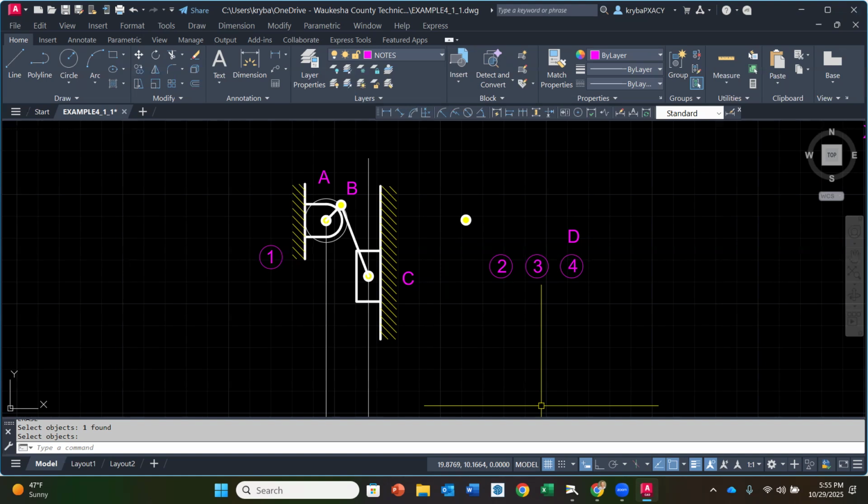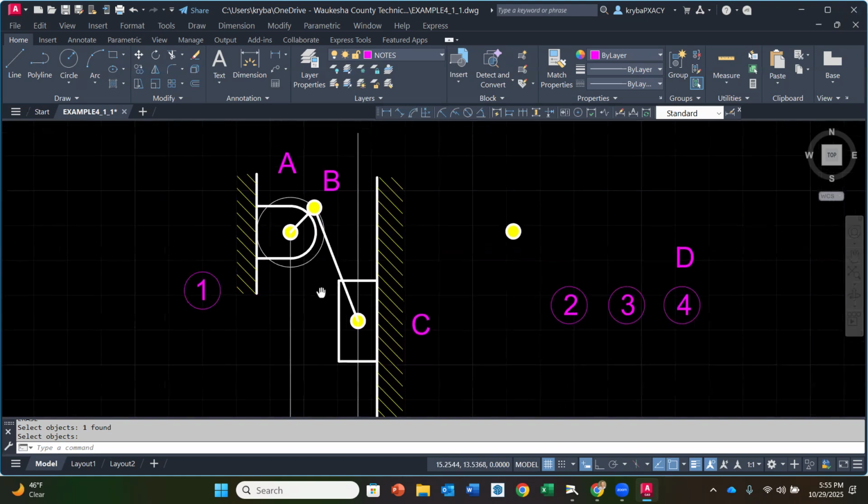Now, the book doesn't require us to do this in this example, so I'm not going to require it on the practice problem, but let's do our mobility calculation really quickly, just to be sure that we have what we're expecting. In this case, the number of degrees of freedom is going to be a 1, okay? This is a 4-bar mechanism. Now, I didn't put all of the labels for the links in place just to save space here. We have got a kind of a confined mechanism.